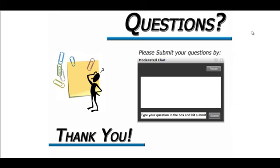This is Chris. Let me add one thing to that quickly. I would say density is important, but what's equally as important is the supply air temperature. So what I would answer that question, I would say yes, it is important to put those supply air fans on variable speed drives, on UPSs at elevated temperatures, yes.